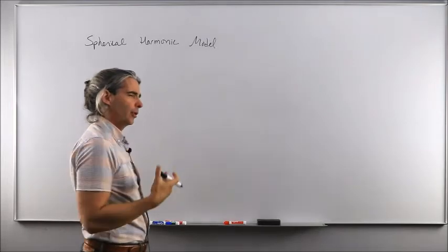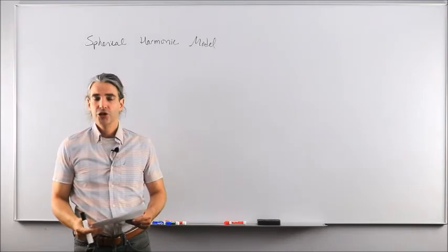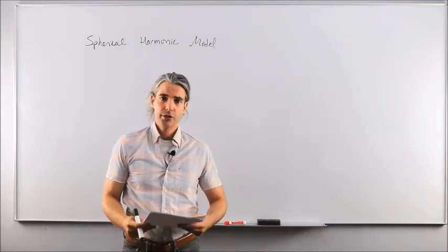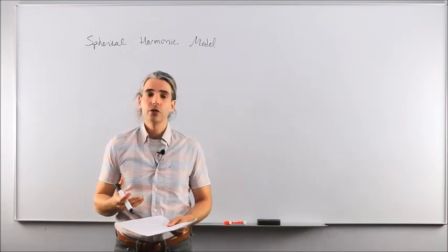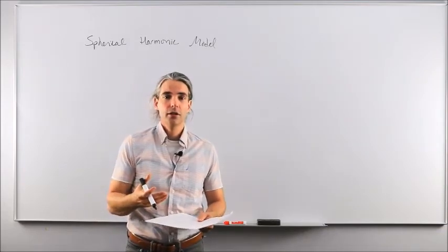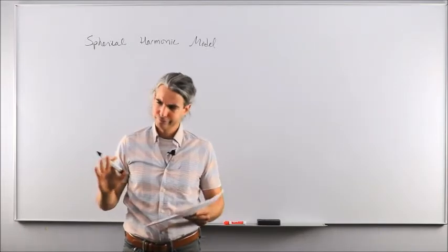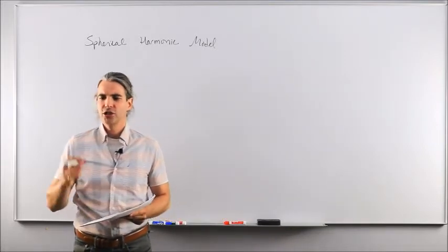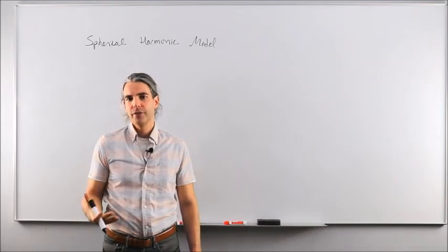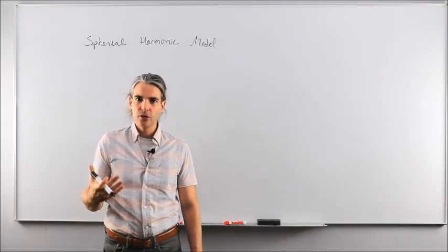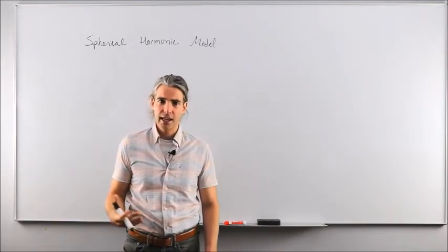Now, I'm not sure if you remember, but from orbital mechanics, we had looked at the J2 perturbation, okay, due to the oblateness of the Earth creating a perturbing acceleration on the spacecraft, perturbing torque or thrust, sorry. I don't want to mix things up too much here. But the J2 was derived by taking the potential function as a double summation in terms of spherical harmonics involving Legendre polynomials and Gauss coefficients and things like that.